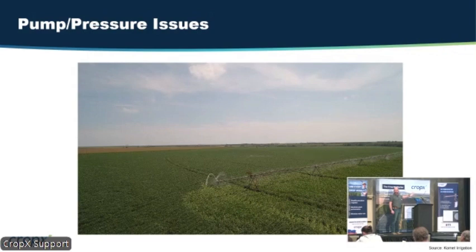Okay? If that thing was designed right, that is not okay, because we are robbing water from one part of the field and blowing it right in the wheel track, the worst spot in the field to put extra water, right? So these little leaks, we're talking about water management. We're talking about inches of water we're trying to navigate through a foot of soil for potatoes. And we have stuff like this out there. Some of this is stuff that you guys can help with, teaching growers why it's super important that we do some of this.